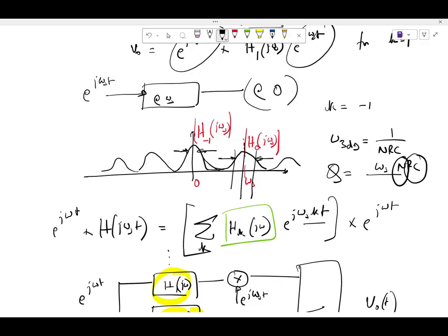And what's more, I can move the omega s also. What is omega s? It's basically a clocking frequency. It's a bandpass filter with an electronically programmable center frequency with seemingly arbitrarily sharp Q factor. Right? Make sense? So that is the power of just one switch. Okay, and that is why these kinds of circuits are becoming very popular in recent years.